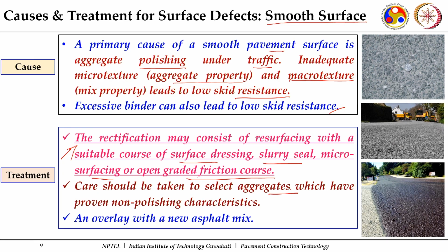But again, it is important that whatever aggregates we select for the surface dressing, and for our open graded friction courses also, we need to ensure that they have good polishing resistance. So, this is again an important aspect.